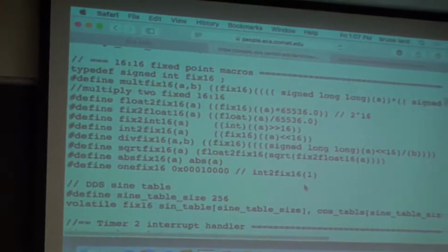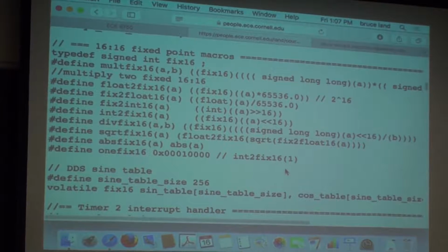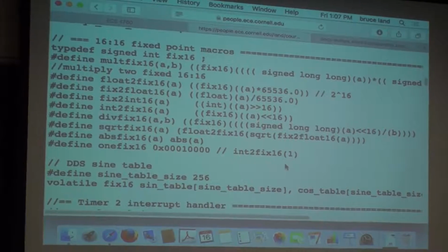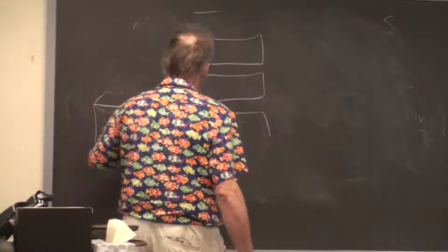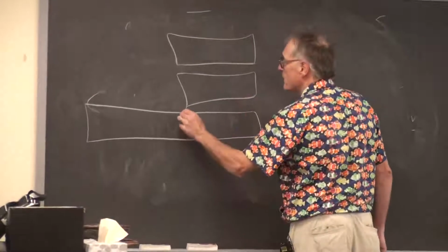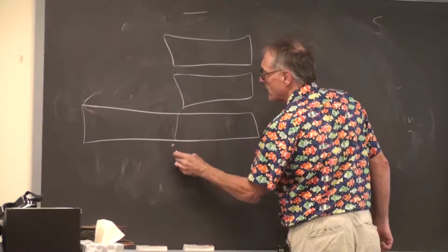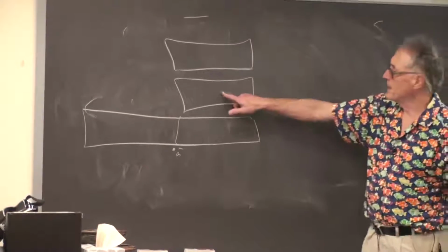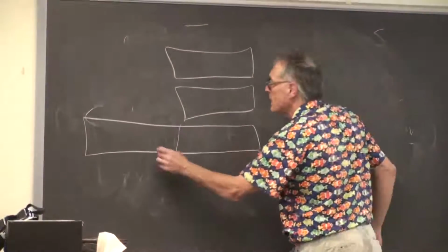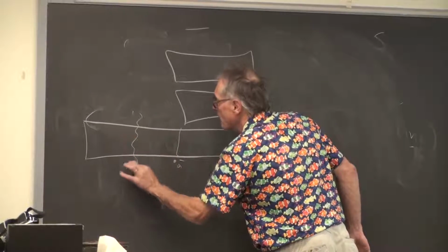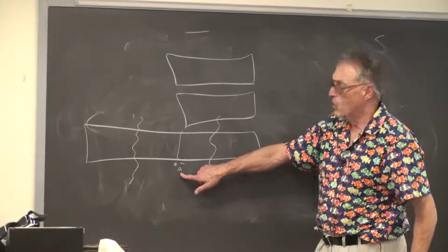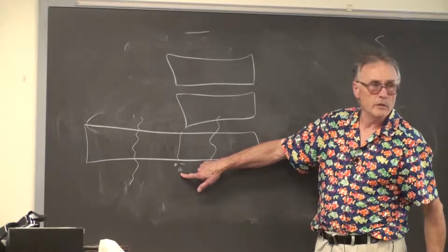And for a multiply, we have to do a small correction. Because when we do two 32 by 32 multiplies, the binary point now is at bit 31. And we need to get it back to bit 16. So the part of the number that we need is the 16 bits just above and below bit 31.